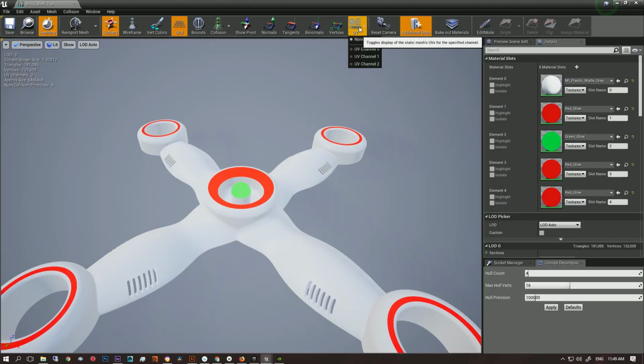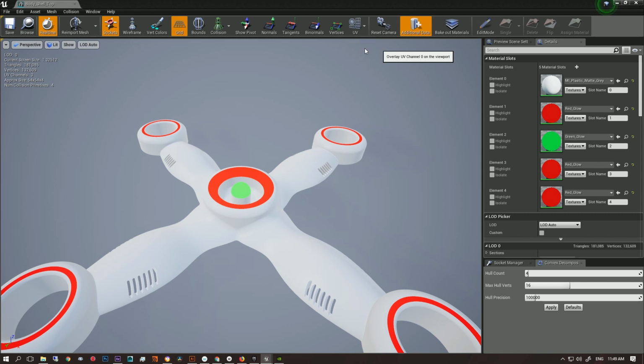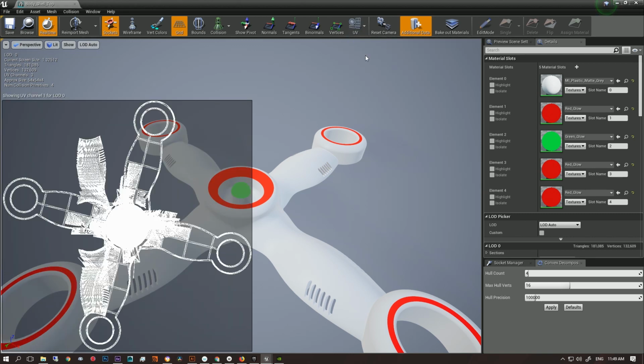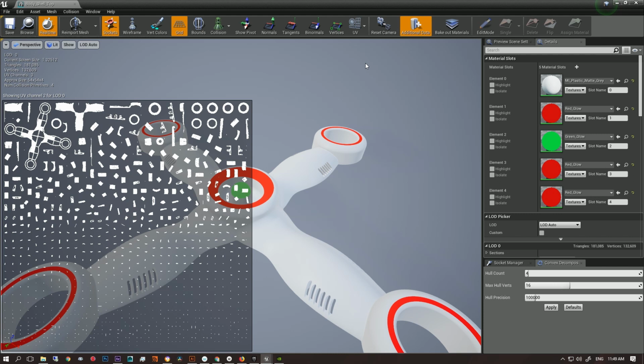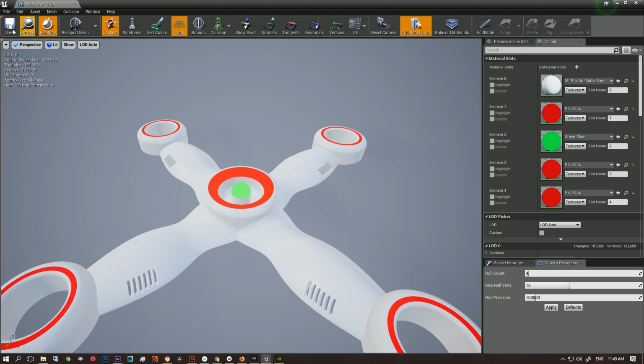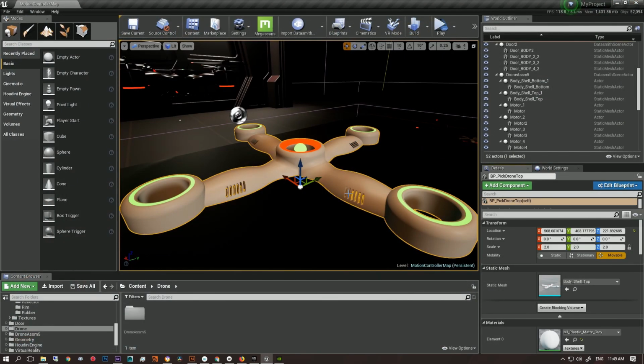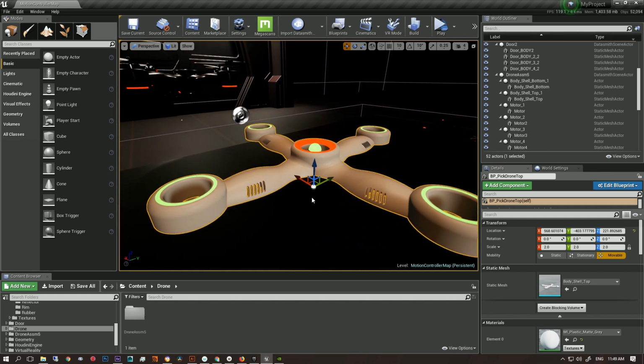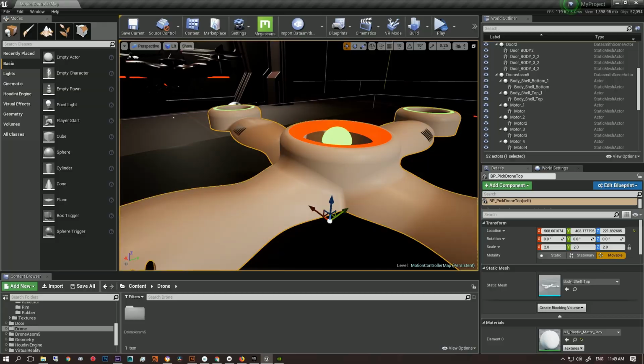One thing that's always a concern when dealing with Unreal are light maps, and while we found that the Datasmith plugin did a great job generating auto light maps, in certain instances we were finding some dirty shadows here and there that were kind of difficult to fix within Unreal. In those cases, it was no problem to just open the FBX files that were exported by Datasmith in Maya, adjust the light maps, and then resave the files.